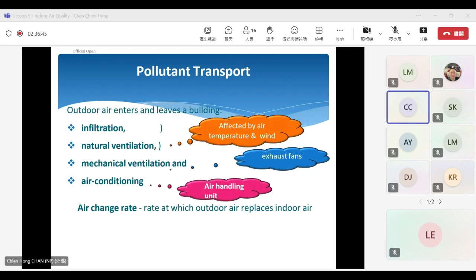Although in Singapore, our building control regulations and the code of practice state very clearly that the fresh air intake must always be at least 5 meters away from the exhaust of your building, sometimes over the years people may forget to properly maintain this requirement, during renovations or when adjacent new buildings come up.